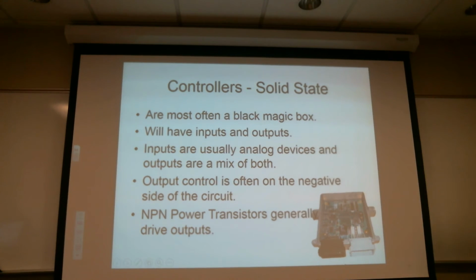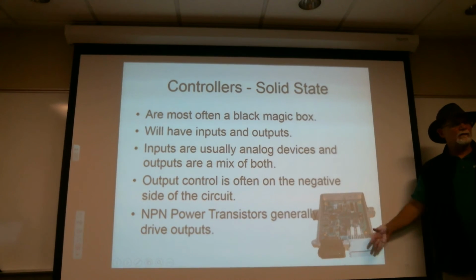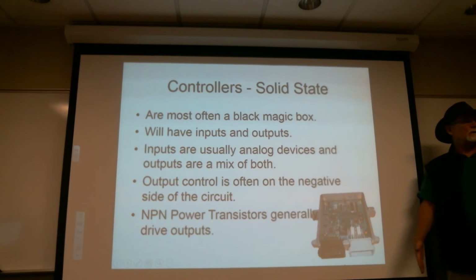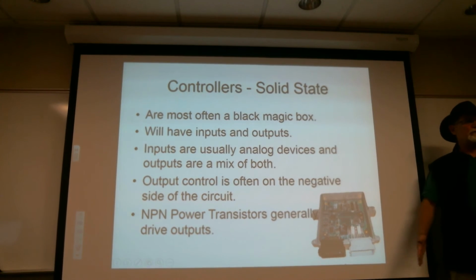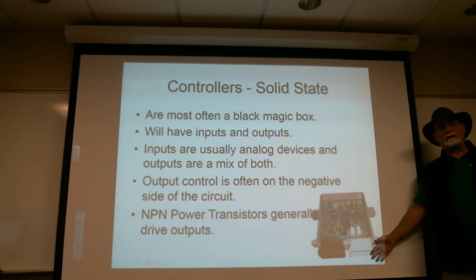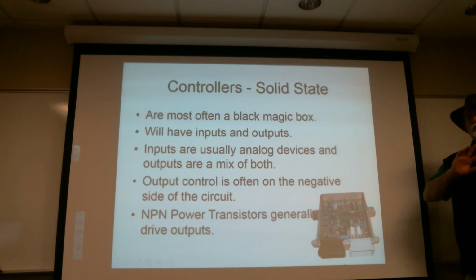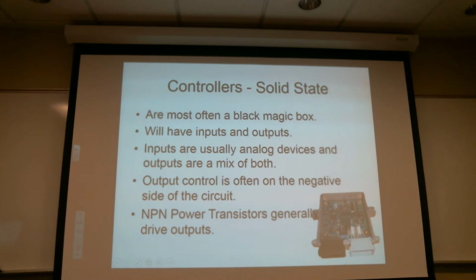Then from there, go back and look at the outputs. I've got good appropriate data, power and ground, coming in. Is the computer actually telling the outputs to do what they're supposed to do? If it is and the outputs aren't doing it, it's the output device. If it in fact isn't telling it, then it's something in between. Now inside here, there are two things that fail. One is something gets fried, and it's usually one of those NPN transistors or an inductive spike reducing diode.